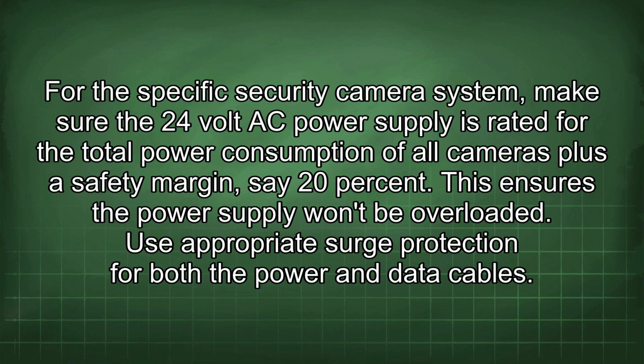For this specific security camera system, make sure the 24-volt AC power supply is rated for the total power consumption of all cameras plus a safety margin, say 20%. This ensures the power supply won't be overloaded.